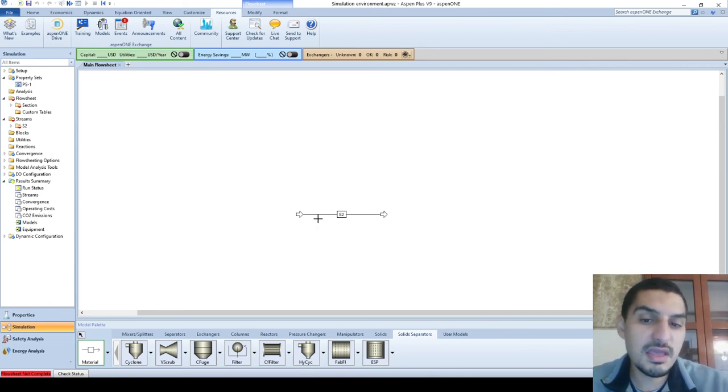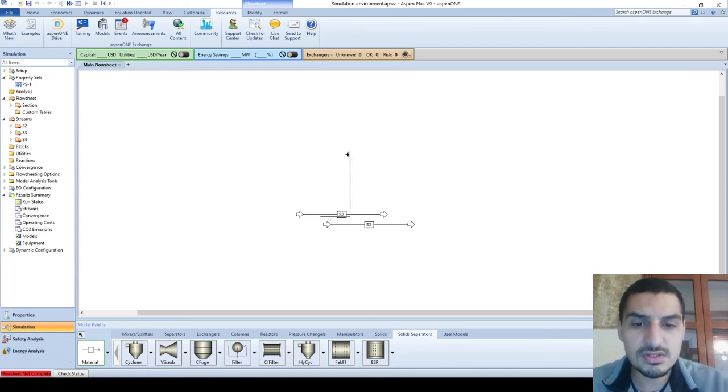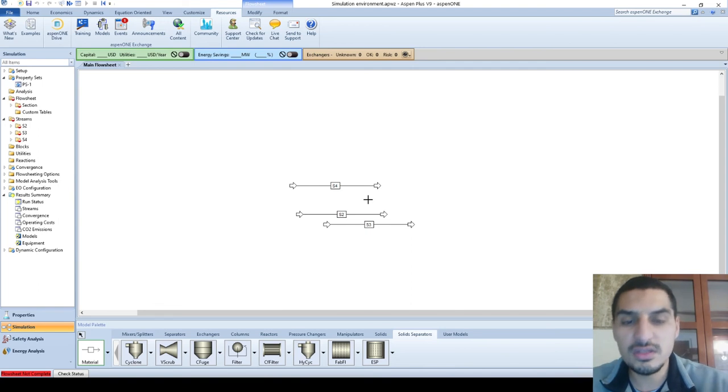So defining a stream, or defining the inputs of the stream, requires double clicking on it. If I double click, it's not gonna go into the stream, but it's gonna define one new stream. Again, this is because I am in the mode of adding streams. It's something that I find students do a lot in the tutorials and the exams. They want to get out of this mode to be able to go into the stream and define it, and each time they click on the stream, they define one more stream. So it's kind of going into an infinite loop of defining more and more streams.